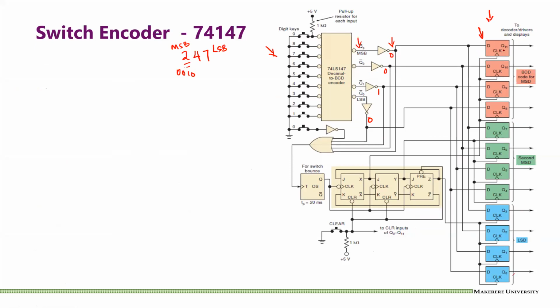You can see that we have Q11 to Q8, Q7 to Q4, and Q3 to Q0. Each of these, and they are in different colors, is a register. Each register is 4-bit, meaning it has 4 flip-flops. And so this technically is a calculator that stores only 3 digits.